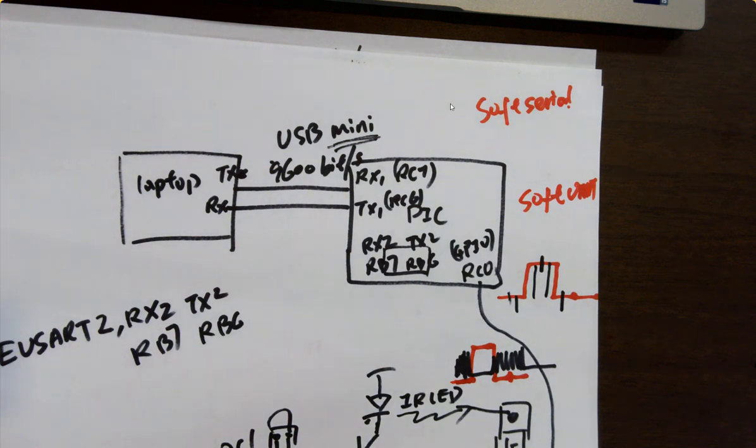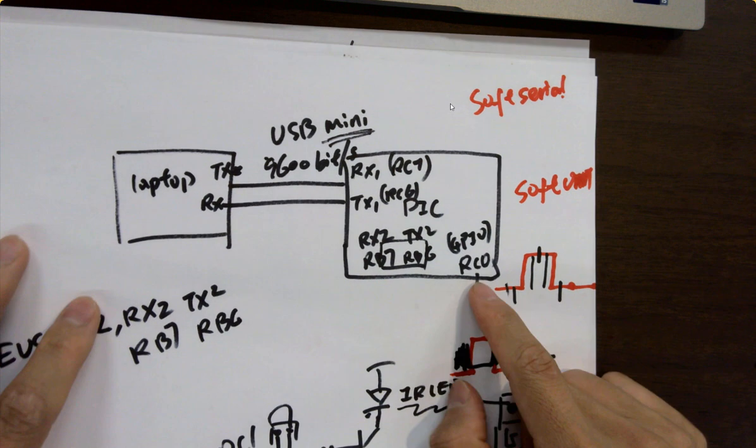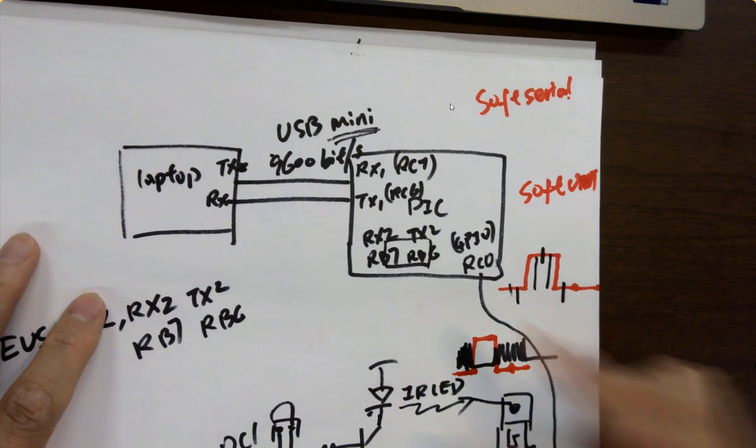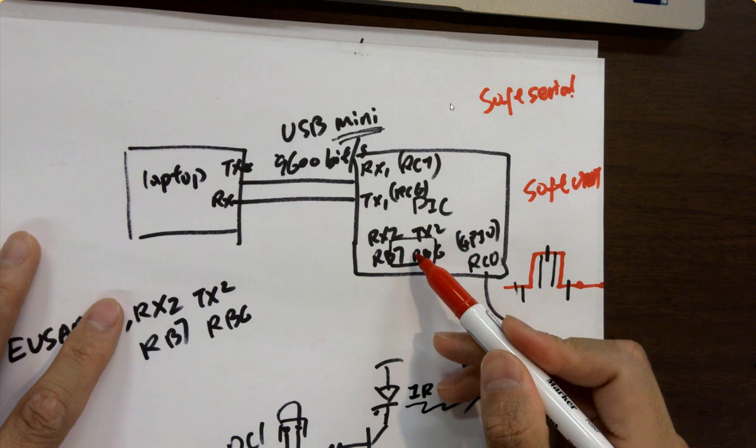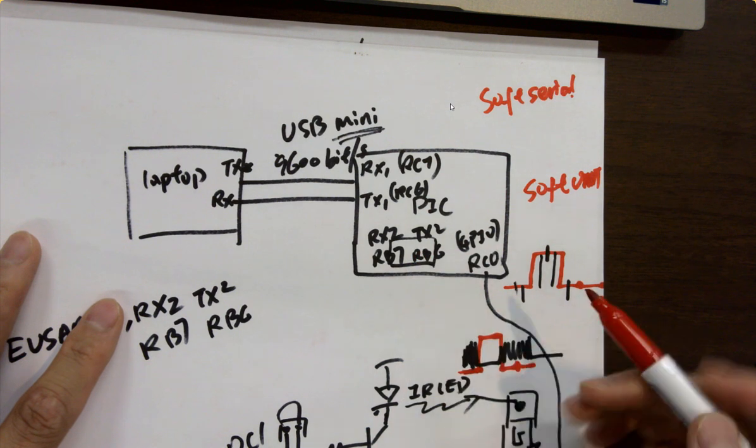The first bit is just a 0 starting bit. You just discard it, you read 0. You know the next ones will be the data, so keep reading for a byte. Then you detect a 1, and you know it's done. So you can write C code to deal with that. Easy. But we don't want to do that, so we can use this hardware to figure that out.